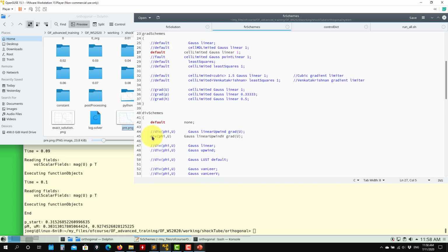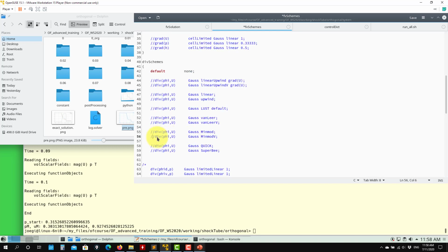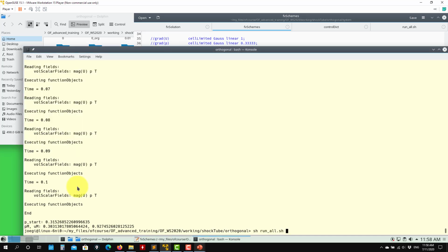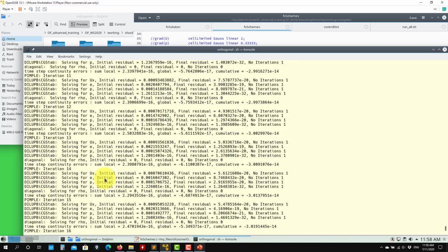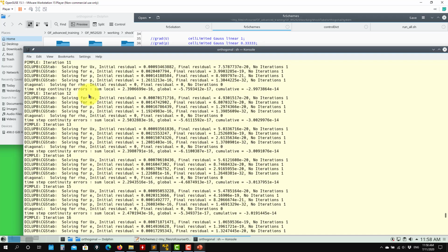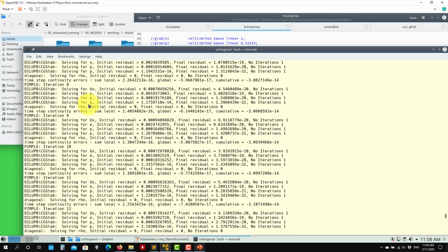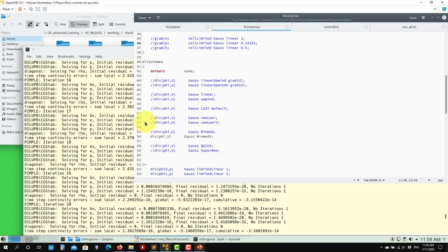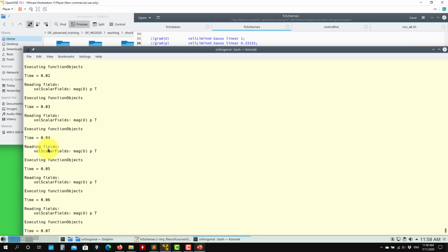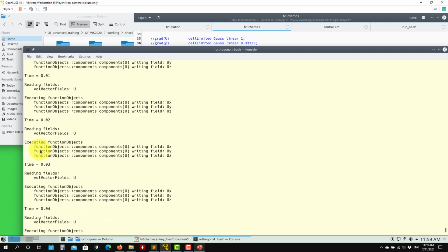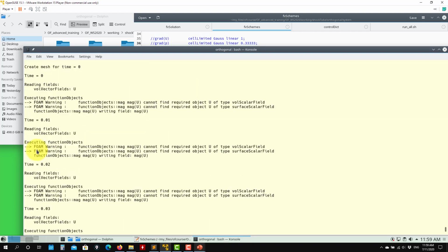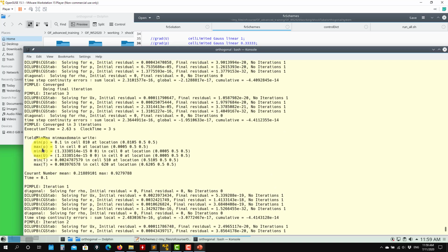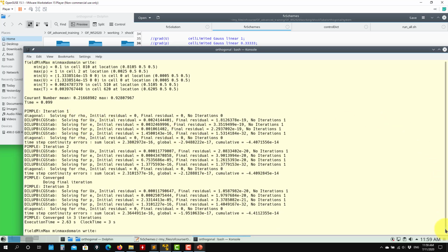So let's move, instead of this one, let's use the minmod. Okay, so let's use V, specific for vectors. We run. See that now it has an influence. By using this one, look at that, it's taking many iterations, so it's not converging. So even changing these parameters will have an effect on your outer loops. It was having problems converging. That does not necessarily mean that your solution will be wrong, but see that after a while it goes to 3. But at the beginning,